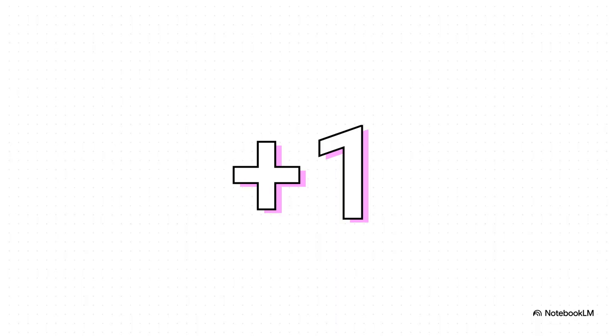But I do have to throw in a quick warning for anyone who has ever studied robotics. There is a classic, agonizing pitfall here. When working with SO(3), you must always, and I mean always, remember that your rotation matrices need a determinant of exactly +1. If you crunch the numbers and wind up with a determinant of -1, well, you haven't just rotated your robot. Mathematically, you've accidentally mirrored your robot inside out into another dimension. Yeah, your simulation is definitely going to let you know you've messed up there.